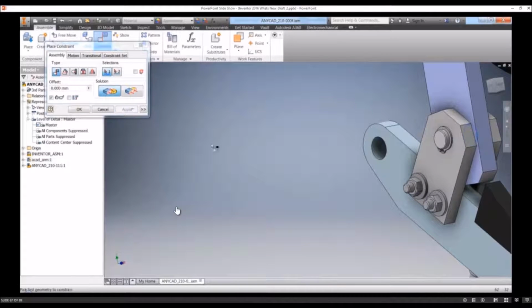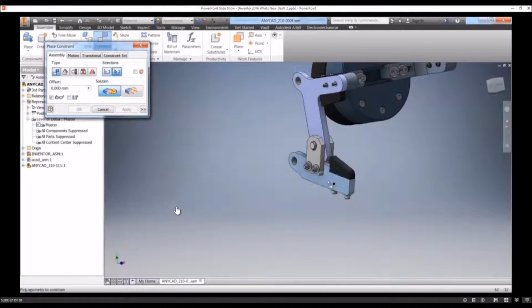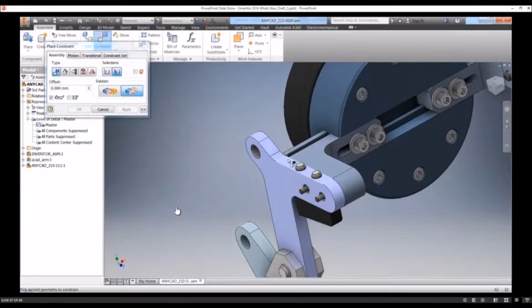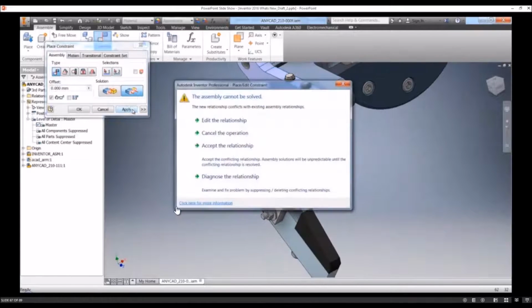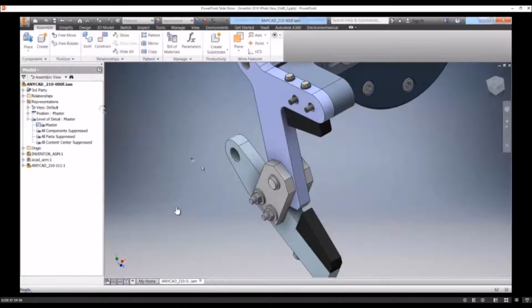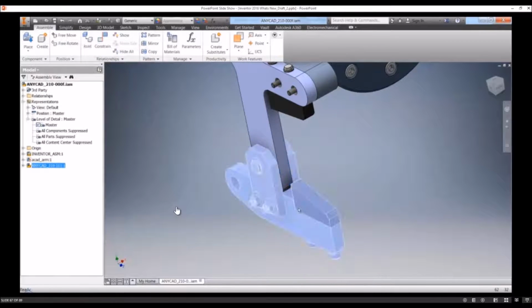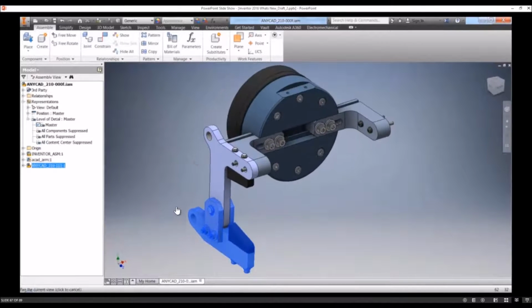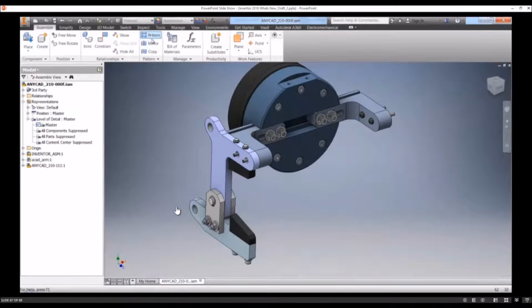I could at this stage as well align it so it still moves in this orientation, so we might just do one more of aligning face to face with an angle constraint. So we'll make this face and this face point in the same direction. Make sure it's on the angle. Work the way through the video. So leave it in position for now. There should have been an angle constraint. Wish I could talk to myself recording the video. So anyway, we've got that in place.